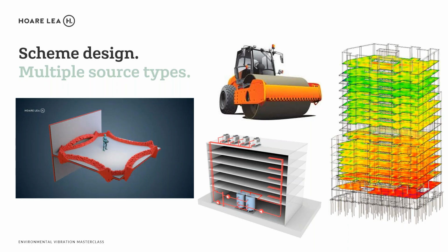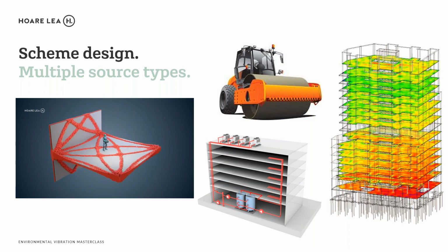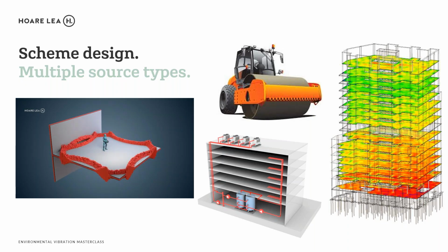For that, we tend to use numerical modeling software to best analyze it, because when we're looking in the region of 1 to 80 Hertz, we are really looking at modal responses of buildings. We have to be very careful that the levels that we predict off the back of our vibration measurements are bespoke to the structure that we're interested in, because the implications are quite big if we're going to start to talk about concrete and cone spacings and so on and so forth.